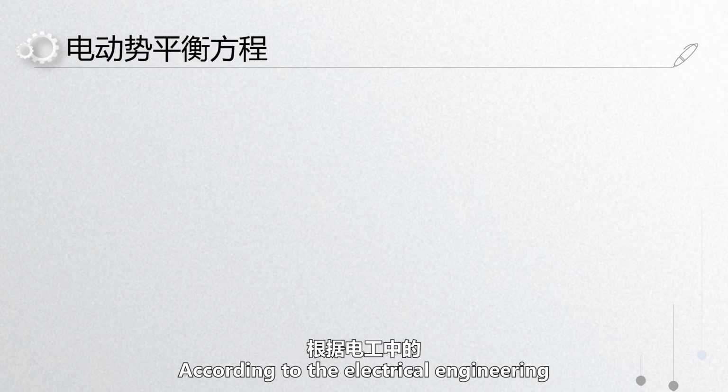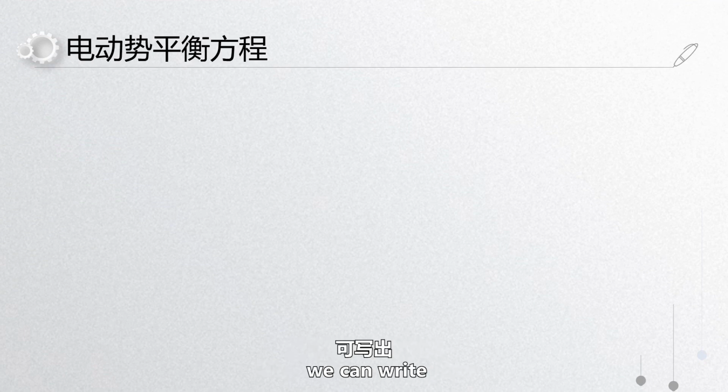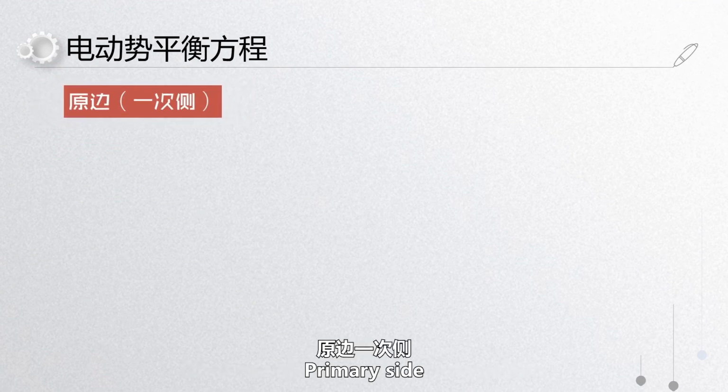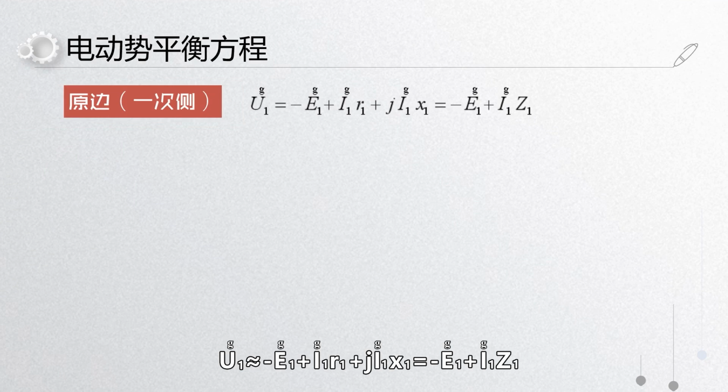According to Kirchhoff's voltage law in electrical engineering, we can write the primary and secondary electromotive force balance equations. Primary side: U1 equals minus E1 plus I1 times R1 plus j times I1 times X1, which equals minus E1 plus I1 times Z1.